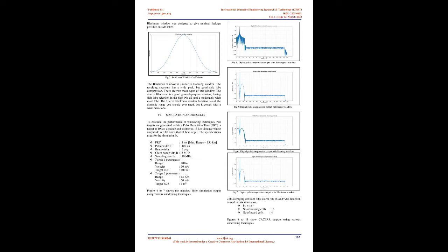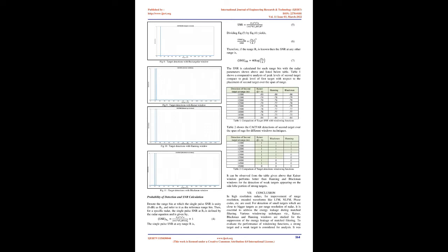If the signal spectrum is rather flat or broadband in frequency content, use the uniform window, or no window. In general, the Hanning window is satisfactory in 95% of cases. It has good frequency resolution and reduced spectral leakage. If you do not know the nature of the signal but you want to apply a smoothing window, start with the Hanning window. Even if a window function is not used, the signal is convolved with a rectangular-shaped window of uniform height,